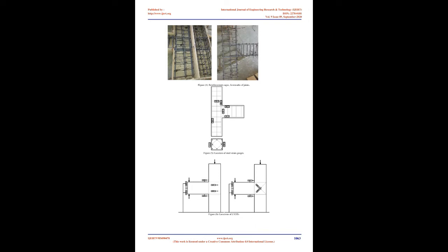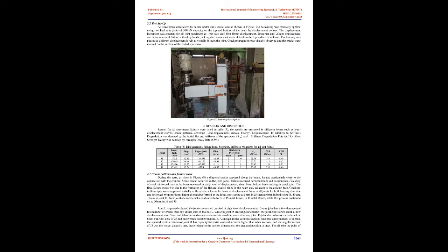For longitudinal reinforcement of all joints, beams and columns specimens, conventional deformed steel bars of 16 mm diameter of high tensile steel with yield strength 542.12 MPa and ultimate strength 626.67 MPa were used, while for beam stirrups, 10 mm diameter bars of high tensile steel with yield strength 483.83 MPa and ultimate strength 572.96 MPa were used. For column stirrups, smooth bars of 8 mm diameter of mild steel with yield strength 358.1 MPa and ultimate strength 487.4 MPa were used.